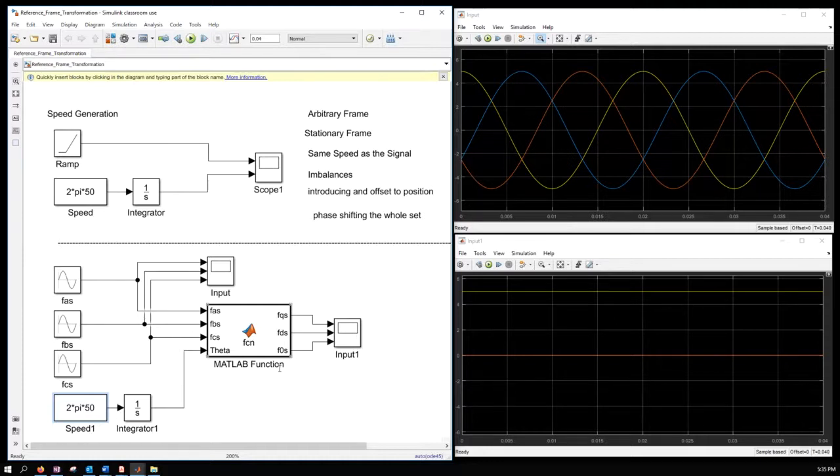Okay, yeah, so you're not affecting your signals, you're not influencing them, but now you take those signals, you convert them to DC, you develop your controller, which will run in this hypothetical domain, and then it'll say, you know, hey, you have 5 volts, I want to regulate it to a certain value, so apply this much of voltage, and that amount of voltage it is asking you to apply will get converted back to this frame using the inverse transform, which will make that DC-like signal from here to an AC that gets applied to the machine.